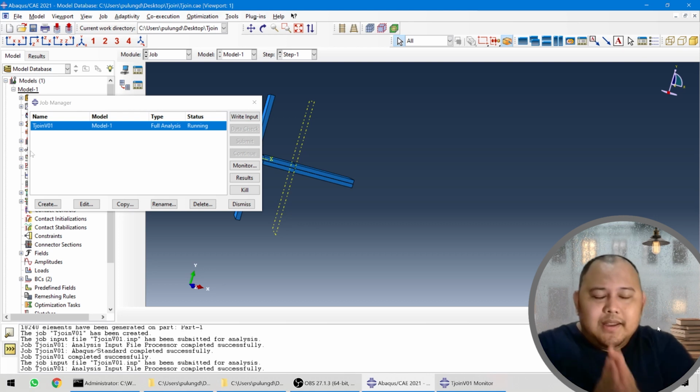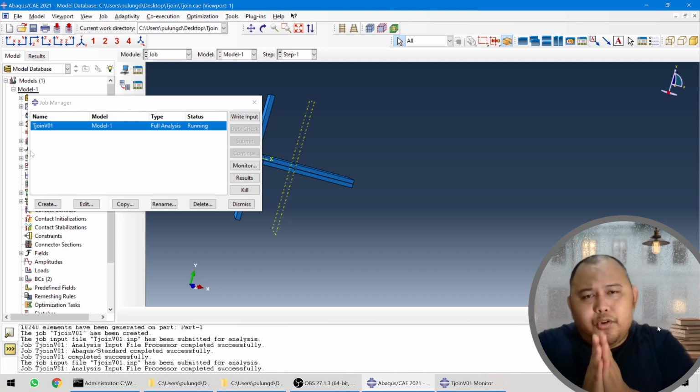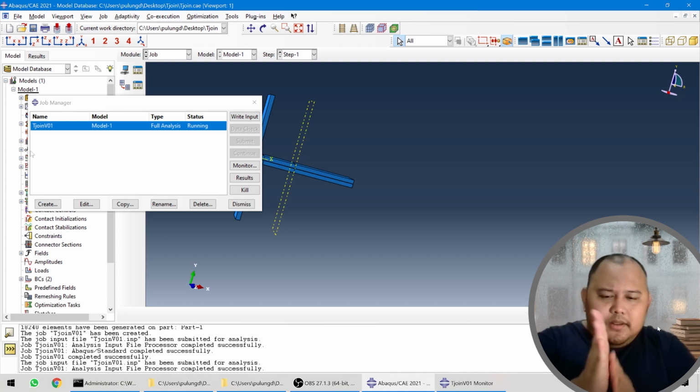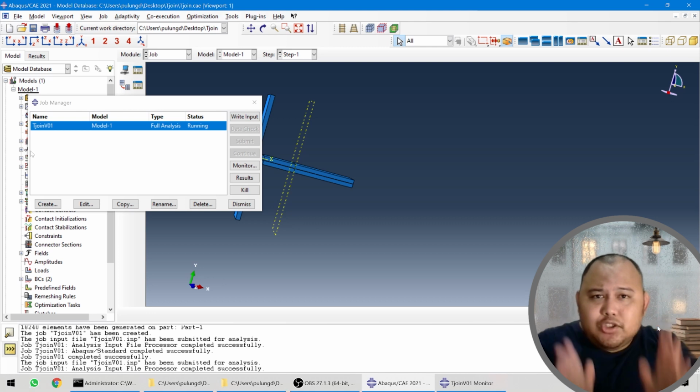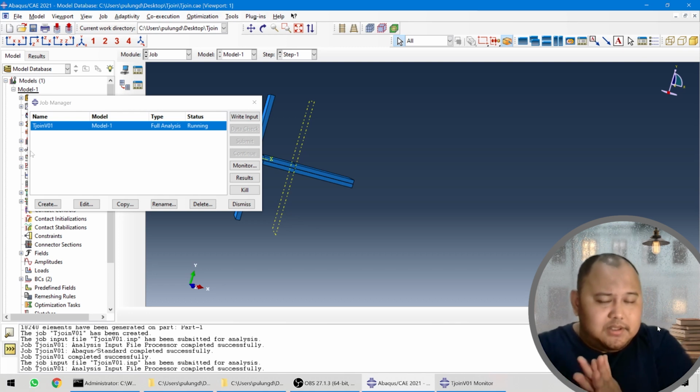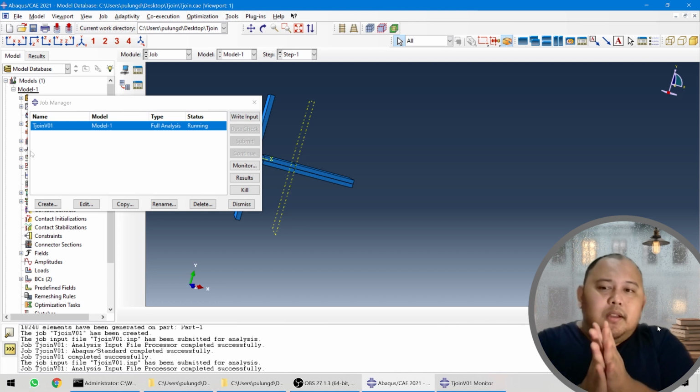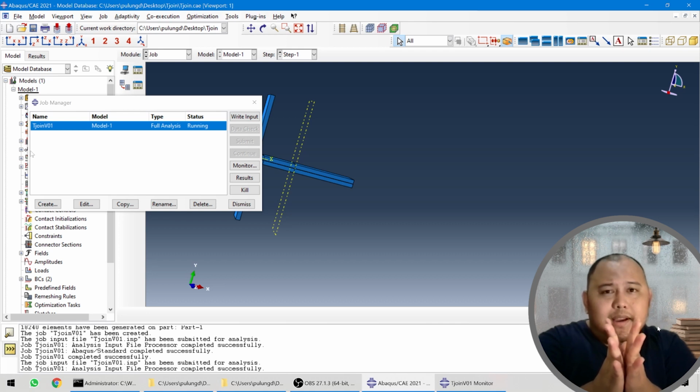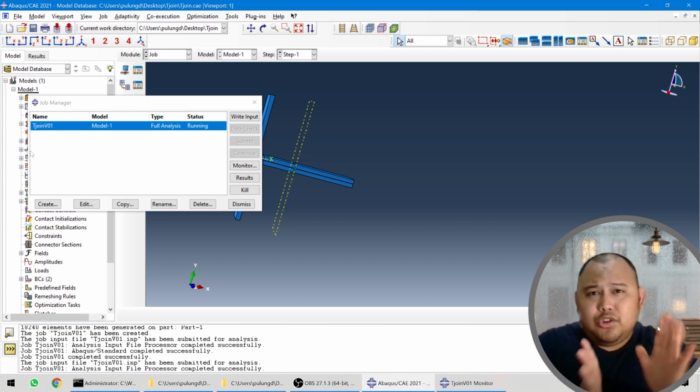I will make a separate video, but the idea is that before you have damage, the adhesive already has a stiffness of K. This is spurious stiffness, a stiffness that shouldn't be there. So theoretically the stiffness should be infinite, but you cannot use infinite stiffness in your finite element solver. You need to put in some number, as large as you can. But if you use a very small number, we create additional compliance in this bonding that shouldn't be there.